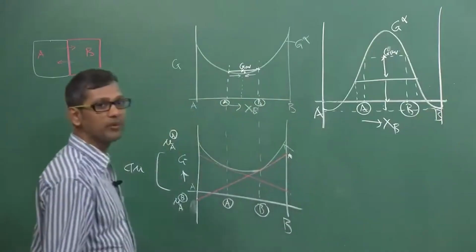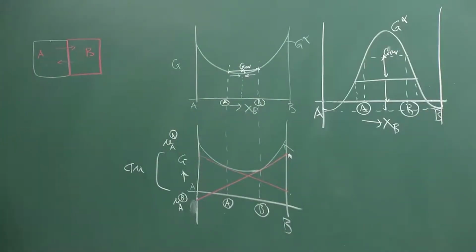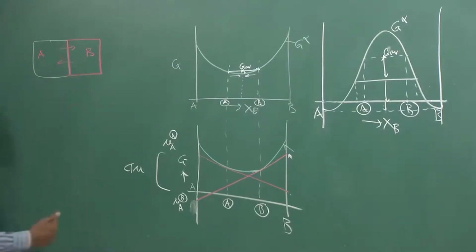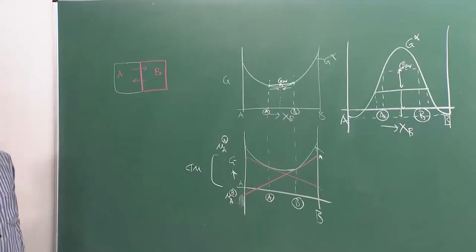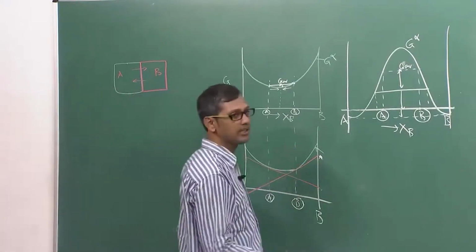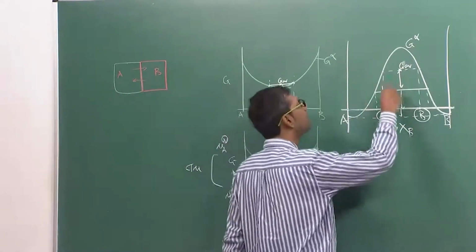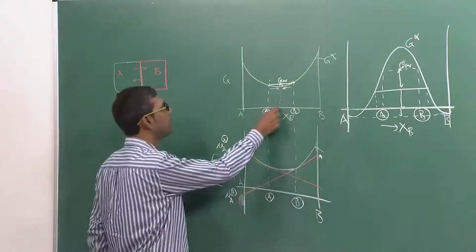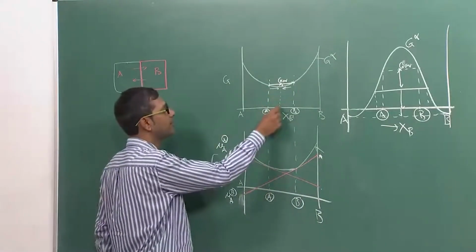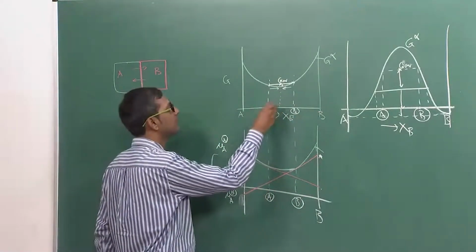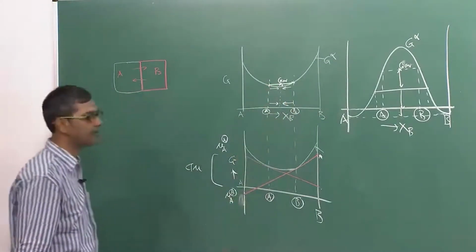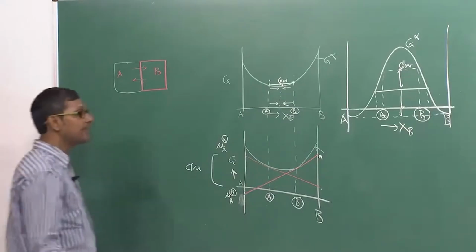So that means what? We are slowly diffusing. The atomic species are diffusing into the regions which are A rich and which are B rich. That means it is not happening down the concentration gradient. It is rather happening up the concentration gradient. Instead of making it more equilibrium like here or more at the center of this composition axis, where things diffuse from here and things diffuse from there and make it uniform, that is how you can reduce the free energy. It is happening the other way.